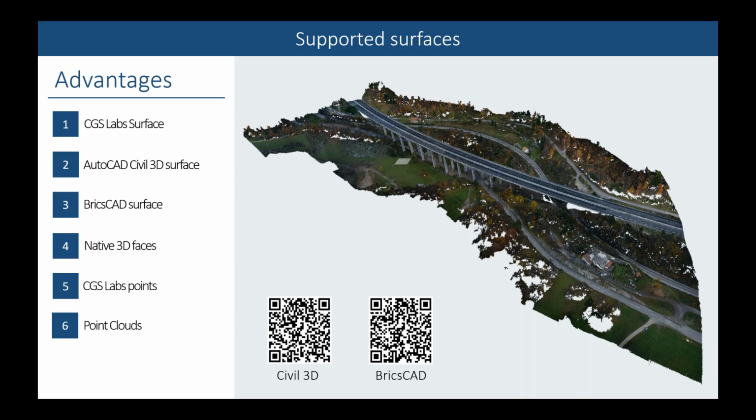In short, no limits. The only important thing is to be aware of which platform you have the Plateia program installed on. So the platforms we support are Autodesk AutoCAD, Autodesk Civil 3D, and BricsCAD. And if you have CGS Labs software installed on Civil 3D, in this case, you cannot project to BricsCAD surface and vice versa. As I already mentioned, designers also use point clouds.